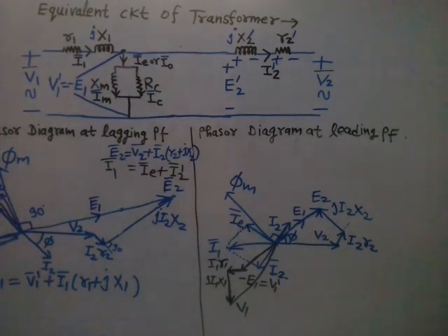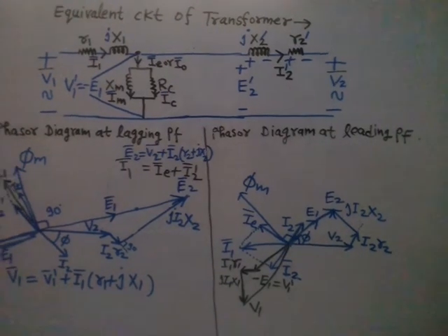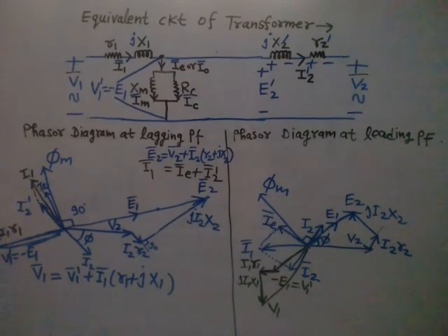Similarly, if you want to draw the phasor diagram at unity power factor, you can also draw. In that case, I2 will be in phase with V2. That's it, and all the remaining steps would be the same as earlier, right? Very easily you can draw. All right.